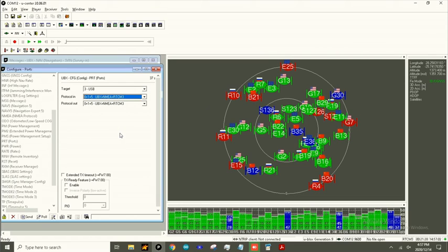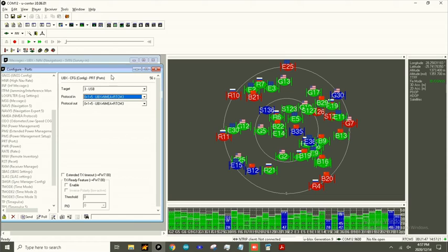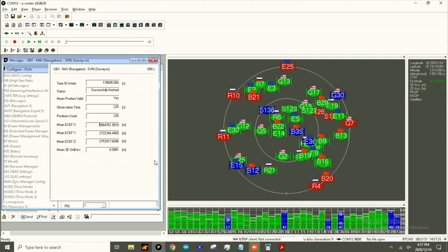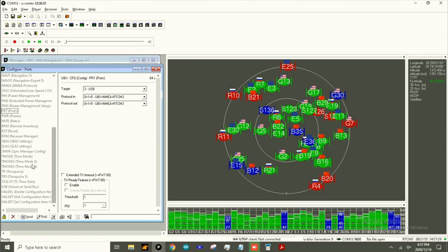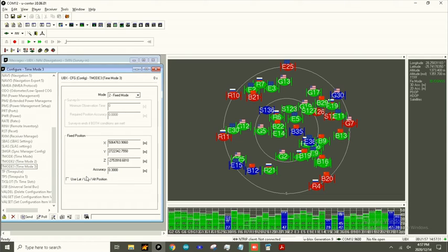So in its current configuration, we are streaming or sending out correction data that's generated by the GNSS receiver based on the observations that we can see after we've provided a fixed coordinate of the receiver, which we did right at the beginning, and which we can get either approximately accurate using the survey-in mode, or very accurate using the PPP mode, which will take quite some time.